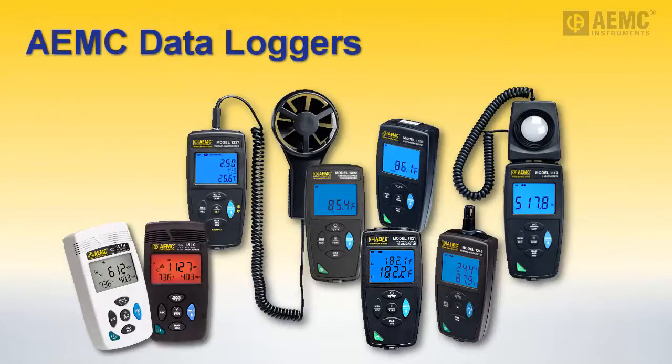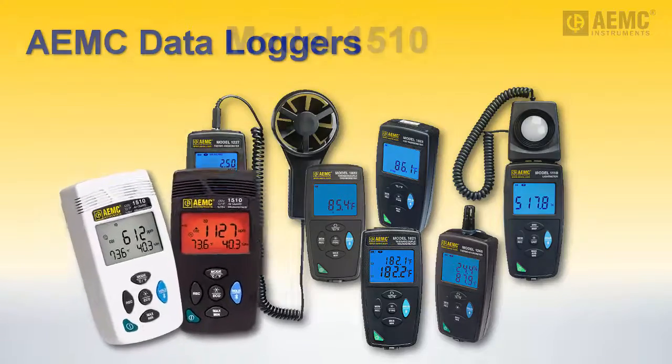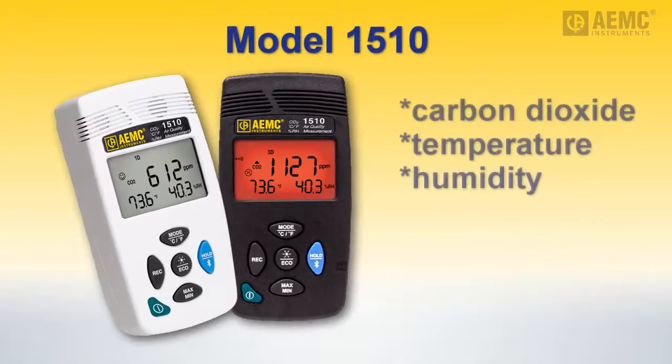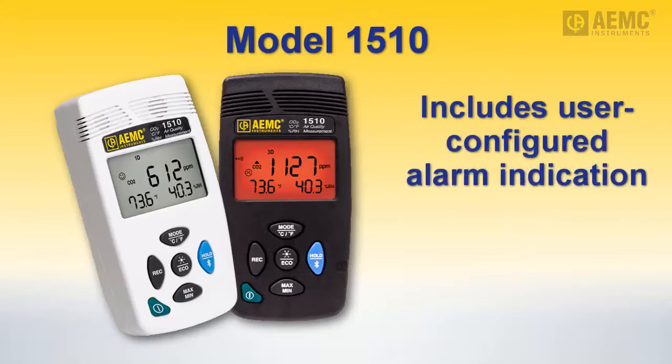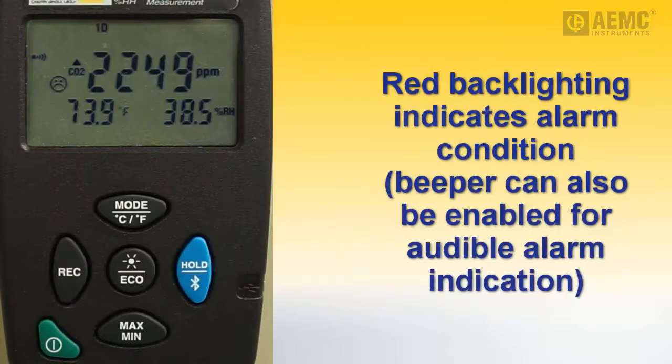For example, AEMC offers a variety of data loggers that can help you monitor indoor environments for occupant health and comfort. One such instrument is the Air Quality Logger Model 1510, which monitors carbon dioxide, temperature, and humidity in the local air. This compact, easy-to-use instrument provides quick and accurate readings and can store up to 1 million separate measurements. The Model 1510 features adjustable alarm settings for indicating when measurements fall outside a specified range. The display blinks with red backlighting when any of the measured parameters exceeds user-selected thresholds.